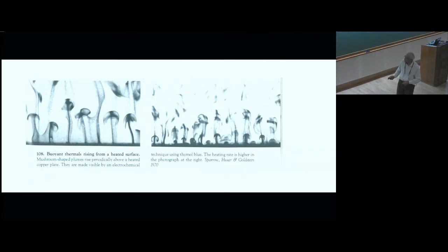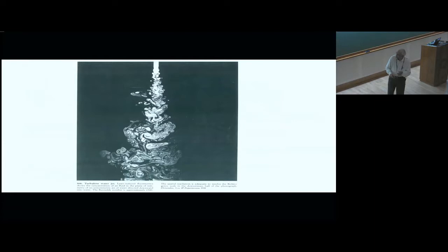So this is one of the electrodes, that is the heated plate. So dye is produced there, and it follows the convective pattern so you can see these plumes which are formed on the plate. Okay? And this is at a higher Rayleigh number, you can see more number of plumes and more closely spaced plumes. So this technique is laser-induced fluorescence, which I'll talk about a little later.